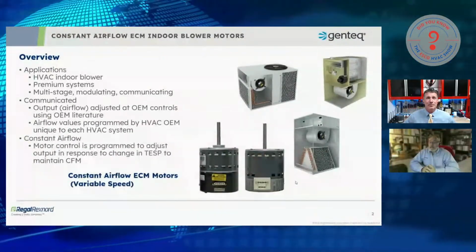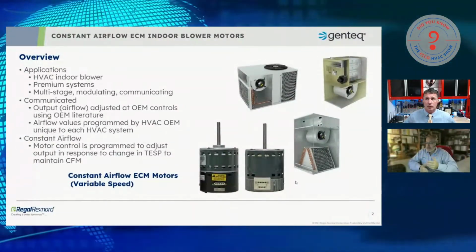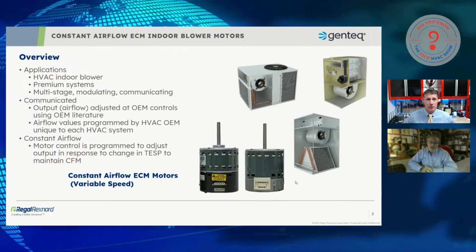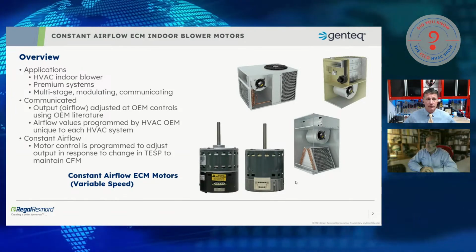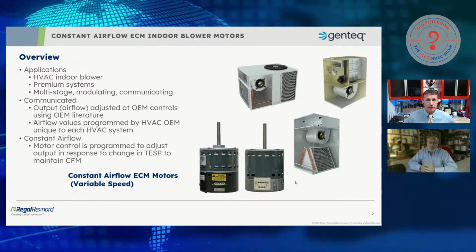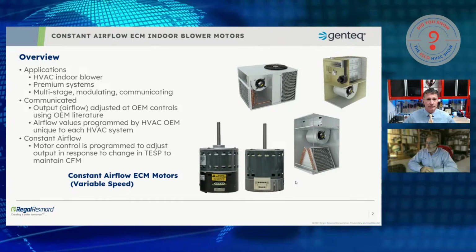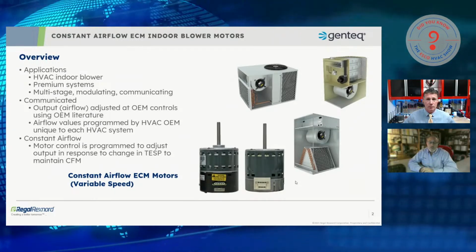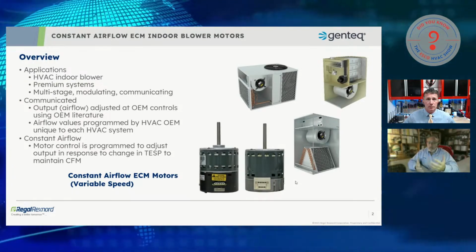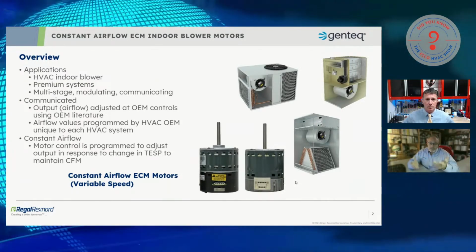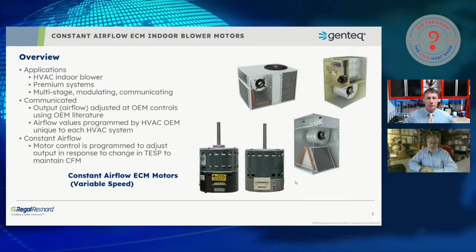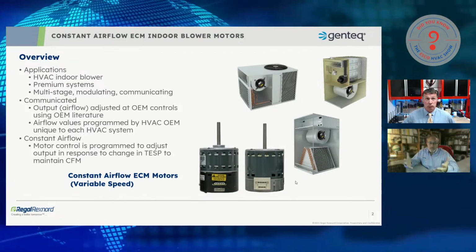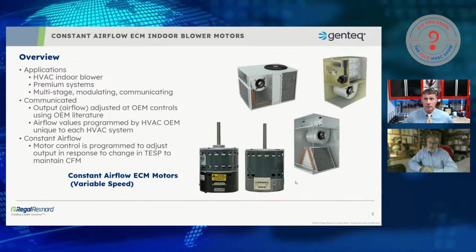That's my hope. And actually, I'll kind of give away the presents early. In my opinion, these motors are actually easier to work on than induction motors, because there's really only a couple of inputs and outputs to check. When we understand that an ECM is a motor that's operated by a control, and that control is a circuit board, microprocessor, whatever, any control diagnostics is just: what's the input, what's the output, and once you understand that, it becomes real easy.